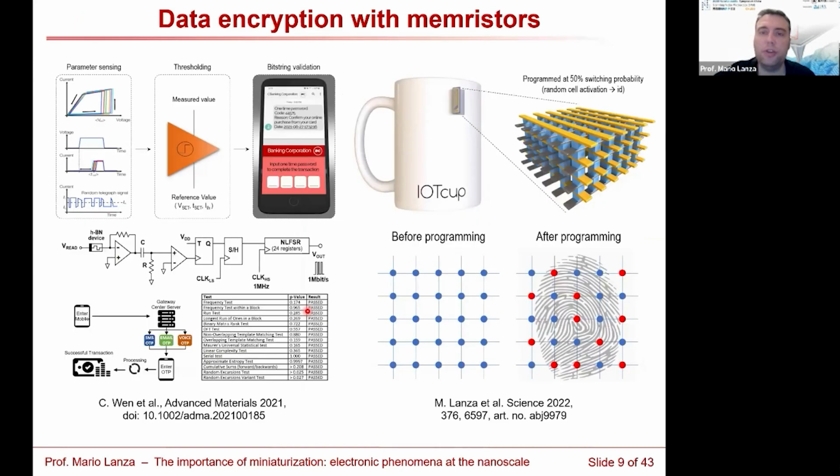And then another additional application is that the memristive devices, the resistive switching devices, show some stochasticity. So some of the parameters, like the switching voltage or the switching time or the current in one state, show unpredictable fluctuations, because the switching mechanism cannot be fully predicted with a very high accuracy, because it depends on the atomic structure of the device in each cycle, which is unpredictable.